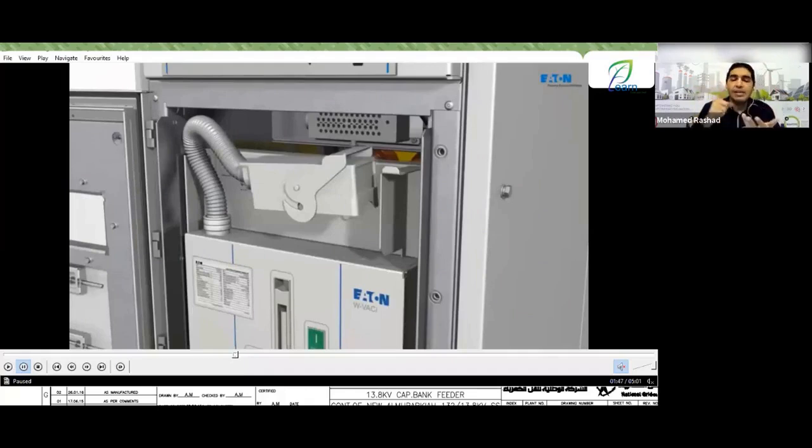And of course, that's very dangerous. First, it's a mistake. Second, you might reconnect the wires incorrectly. With too much fiddling and fitting, you could damage the terminal block or the socket. You might accidentally cut wires, which can cause a lot of problems. So what happens? Anything that goes into the circuit breaker comes out here, all through this plug. This plug has many terminals.